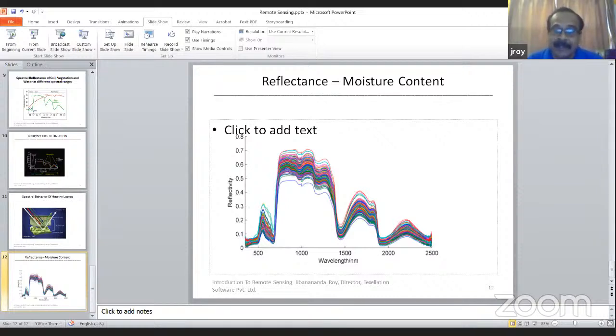In a hilly area, you will find the distance between 2 points is not the same if you take the images from different directions. So you must do the correction for the distortion due to the Earth's curvature. Now, since you know the location of the satellite, the angle and the Earth curvature, you can model this technique to rectify these errors.